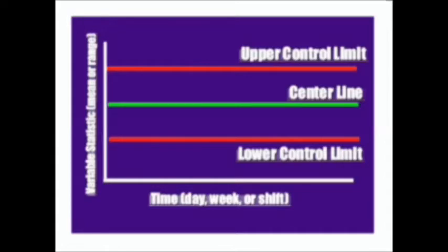And the idea here is a control chart can be used to monitor any event or changes in process, whether on time domain or time increment or location increment or machine type, lot type, factory type, and so on. The vertical axis, on the other hand, represents the variable in question: the strength of material, the weight, perhaps rejects or number of defects. That is the vertical axis.